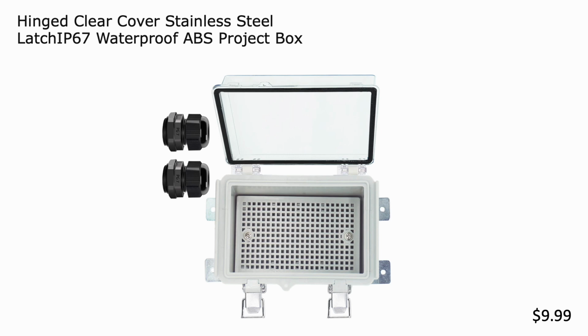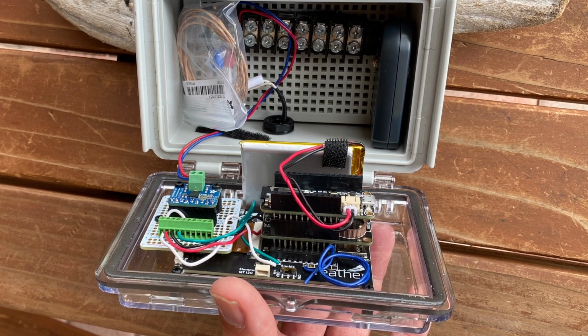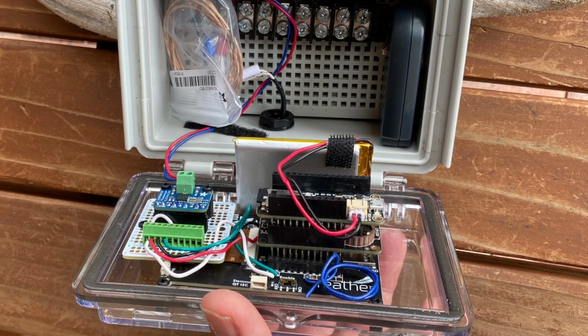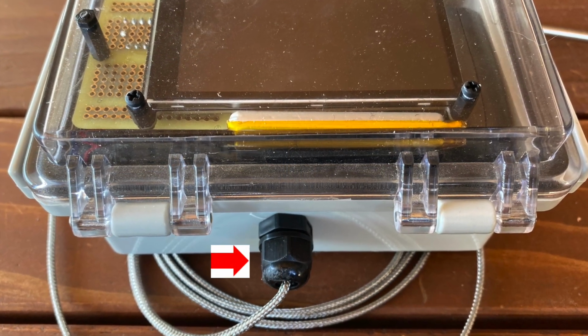We also picked up this hinged clear cover ABS project box, which makes our data logger a little bit more robust with respect to field conditions. And finally, our local makerspace donated one of these terminal blocks, which really helps improve the connectivity between the thermocouple and the thermocouple amplifier. With those improvements in hand, this is our latest prototype, showing our original hardware embedded in an IP67 rated weatherproof enclosure. And finally, here's our improved thermocouple, which is fed into the box via a waterproof gland.